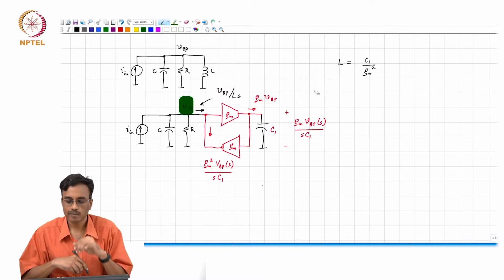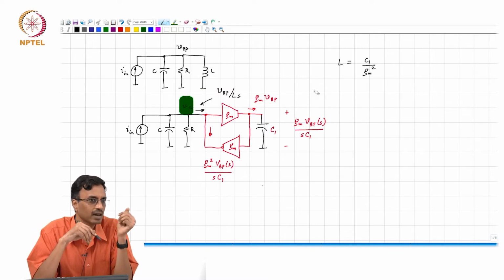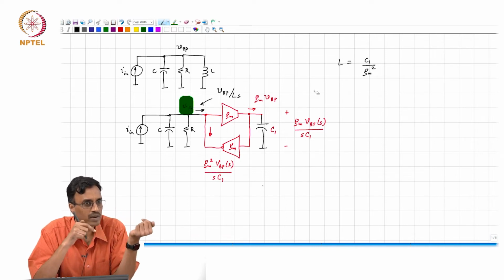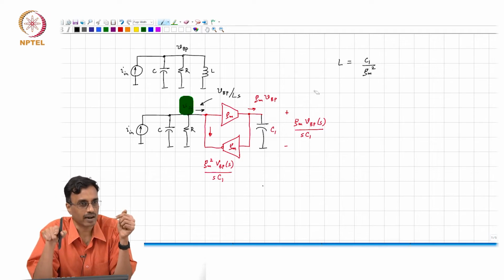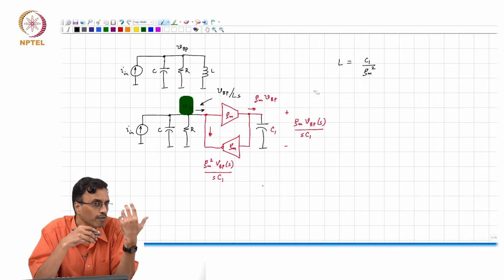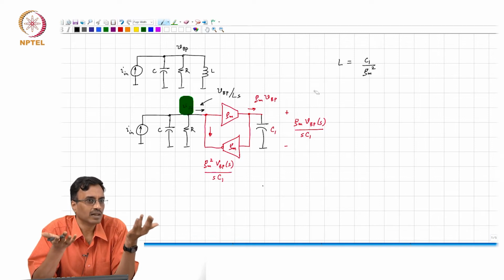And all that this box is doing, the contraption in red, is taking the capacitor voltage and making it look like a current, and taking the input voltage and making it look like the capacitor current. So, this way it is simply interchanging the roles of voltage and current, okay, which is exactly what the difference is between a capacitor and inductor.